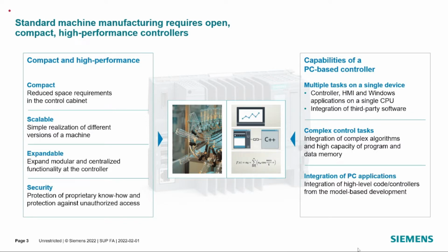In addition, you have the flexibility that, because the Windows is already there in the open controller, the Windows part can be used for HMIs like TIA WinCC Advanced, which comes with different tags. You can order directly with the tag licenses, and the controller is there by default. So it is a controller and HMI in a single system. The only thing you have to take care of is the screens. You can have separate screens, and other third-party applications can also continue running in the same Windows.